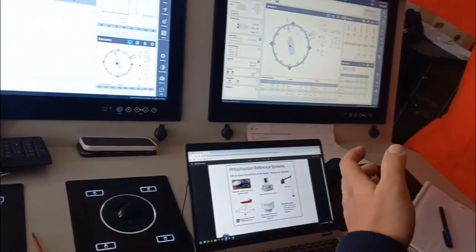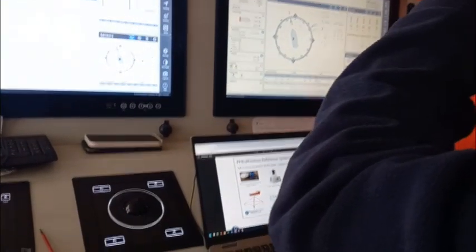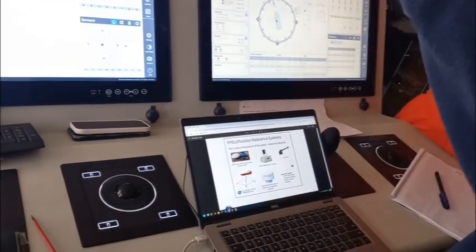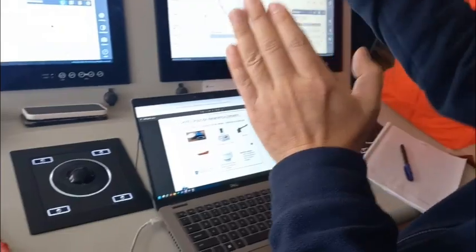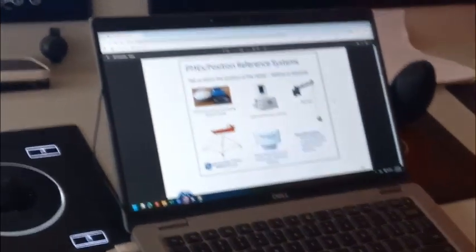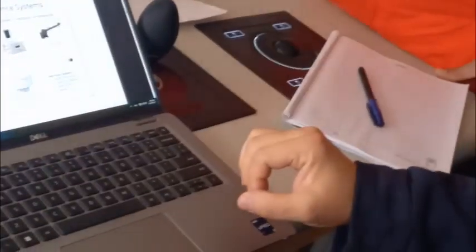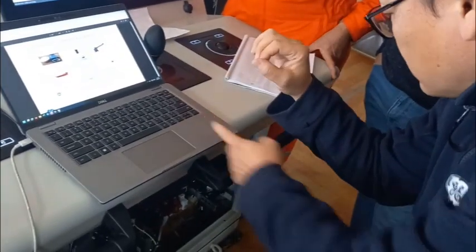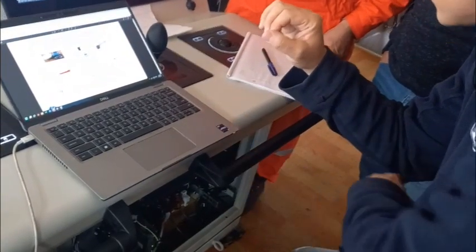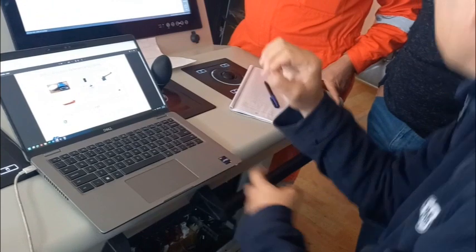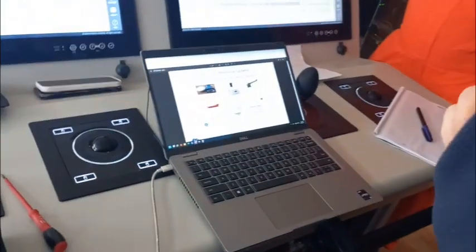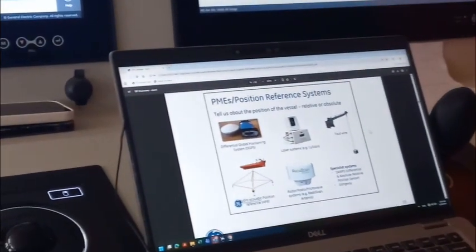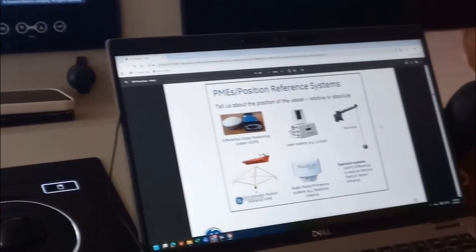Is it elevation or what? Elevation is the angle from the horizontal side. Let's say this is our vessel, this is the platform. When the vessel is moving up and down, this angle, the elevation, changes. So they have to give this signal that's changing. So they give us three axes. How can they give this signal to the DP? This is the gangway control system. They will calculate these angles.